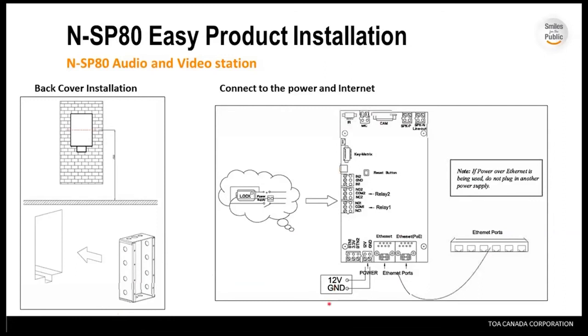If you're outside of the POE type distances and so on, maybe you have to add local power. So that's one thing as an option there, or again, it can get power straight from the POE. One thing to note, if local power is being used, don't plug in the POE, so don't double up the power. If you are on a POE switch giving it power, don't double up the power.